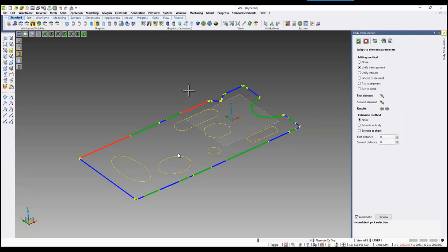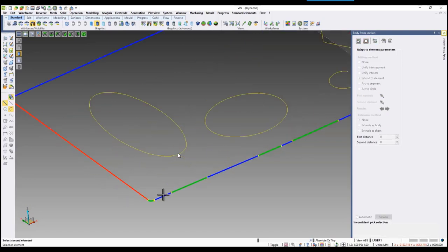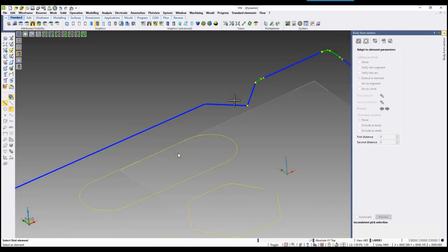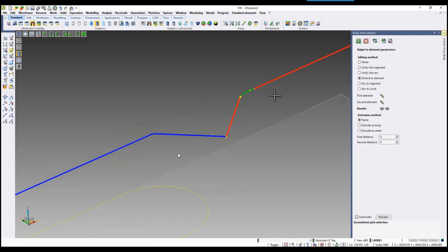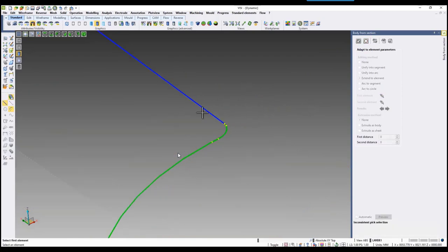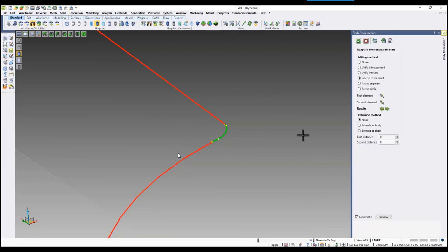So you can highlight different areas, you can clean up the mesh model, you can unite those into a unique segment, and you can extrude the element. You can see how we are cleaning up this mesh model using the body from section option, basically cleaning it up to make it, let's say, one segment, one arc, and so on. Think of it kind of like concatenate curves, but you're actually simplifying, joining these curves together, making it into one entity using this command. Within here, you can select different areas and start extruding those models out in relevance to the section that you created.